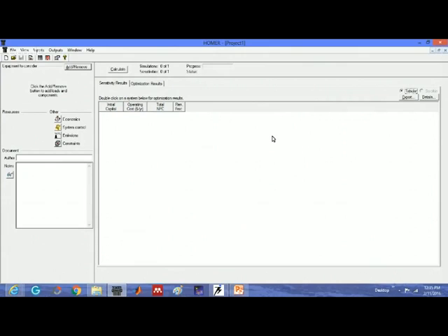So the second thing is, what kind of load we are going to use. If we have a DC load, the system will be this. Sorry, if we have an AC load, the system will be this one. If we have a DC load, we don't need a converter, right? We are not using AC, so we don't need a converter. The load, the system and the battery are all on the same bus. Nothing is required.